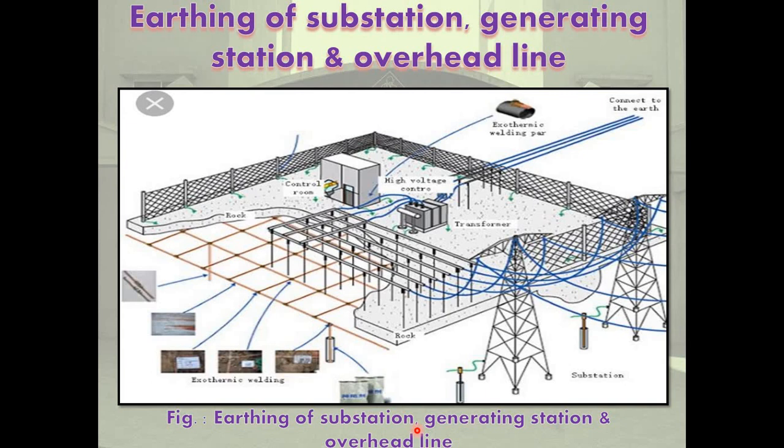Next is EHV AC transmission line switching duties. An EHV AC transmission line has distributed series inductance and shunt capacitance. Opening a long transmission line and closing a long transmission line tend to produce switching overvoltage in the range of 2 to 3 per unit. Switching duties of significant switching overvoltage include opening unbalanced or unloaded lines, reclosing on a charged line, opening a line on short line fault. Now, protective measures and preventive measures.